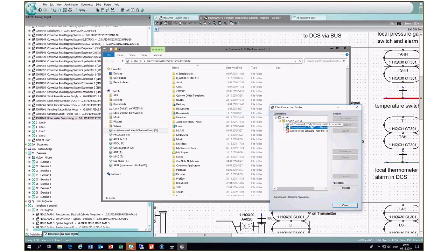And now, if I want to drag and drop a document into Comos, into the Navigator, which is possible, then you need to have a Comos Explorer. Okay, so that's the reason. Because you have to be on the same server, you can't go from one server to another and drag and drop. This doesn't work. You have to be in the same. So your sessions have to be on the same server.